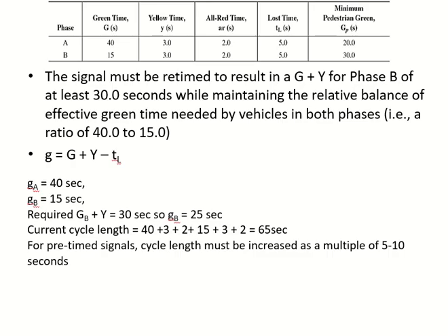Okay. Anyways. So now the problem is we are 10 seconds short. Green plus yellow plus all red should be at least 30 seconds. Got it? Right? Okay. Now, so we have to make it 30 seconds. In order to make it 30 seconds, which timing can I increase? I need 10 seconds more, right? Where should I add these 10 seconds? Green time, obviously.